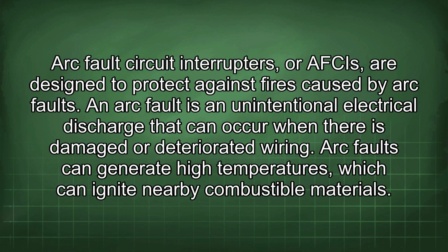Arc fault circuit interrupters, or AFCIs, are designed to protect against fires caused by arc faults. An arc fault is an unintentional electrical discharge that can occur when there is damaged or deteriorated wiring. Arc faults can generate high temperatures, which can ignite nearby combustible materials.